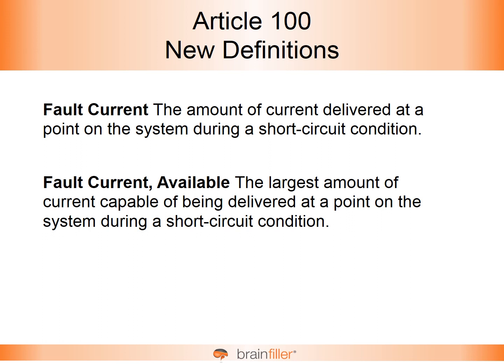A lot of people think that the maximum fault current is the worst case when it comes to the incident energy. Well, the maximum fault current may be the more explosive case, the more energy per time or per cycle, but you also have to be careful because lower fault currents or minimal fault currents might actually be the worst case when it comes to incident energy. A lower fault current could result in a protective device taking longer to operate. So even though the event may not be as explosive or as much energy per time, with a greater duration, you could end up with a larger total amount of incident energy.